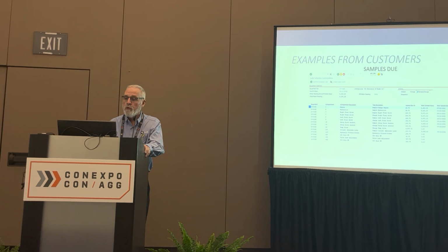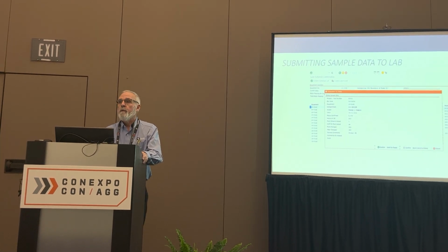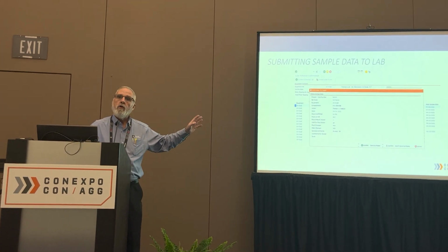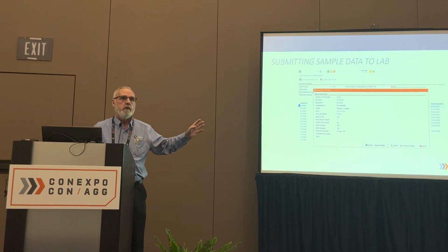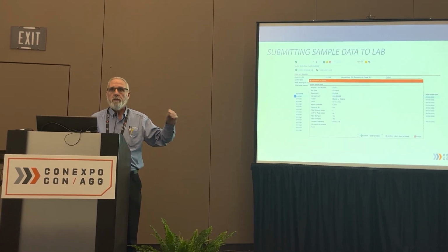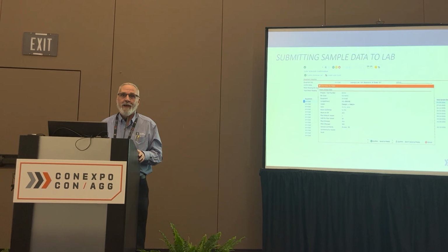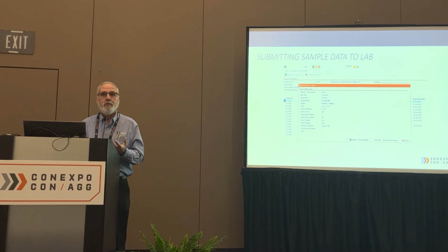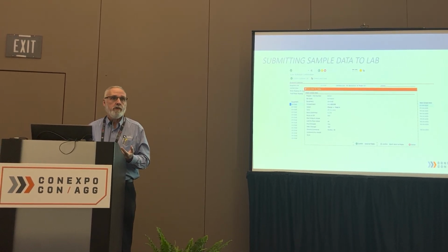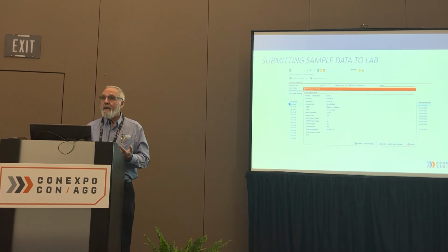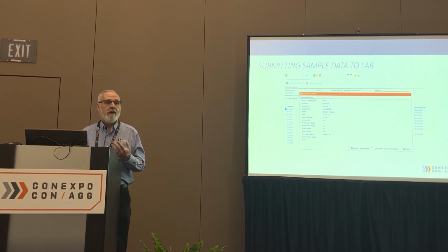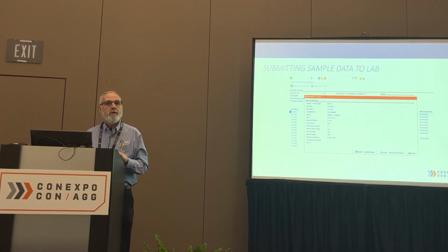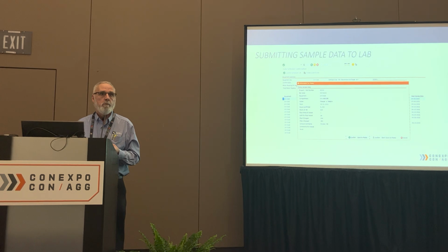When the sample was pulled, this pop-up would appear on their CMMS, and it includes all the information the laboratory needs to process your sample. All that stuff that some of you are still handwriting on that label. And think about a handwritten label. I mean, you've seen them. They're smudged with oil, handwriting from the technicians, almost impossible to read. Having this data accurate, where the laboratory can read it and associate it with the correct component, is vital to a quality fluid analysis program.